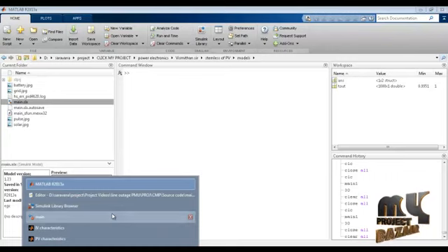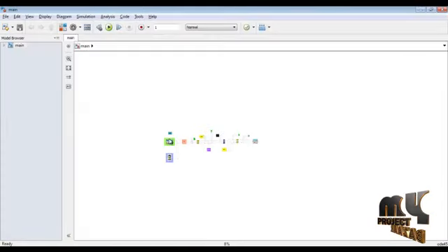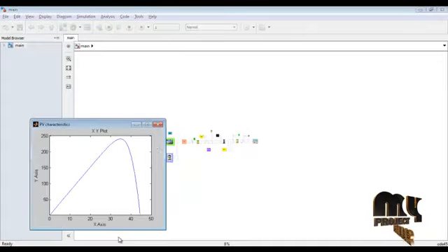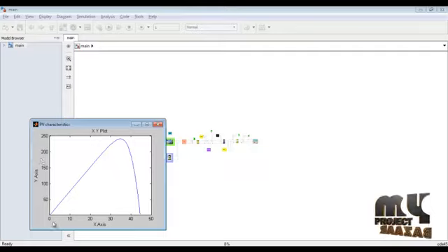This is the general architecture modeling. The general architecture consists of the solar panel, battery, and voltage source converter, and the different models are gathered as per the circuit diagram of the paper, with the ripple filter, load, and grid, all implemented accordingly. Next we see the results. This is the PV characteristics for the solar panel. The x-axis is voltage and the y-axis is power. It reaches nearly 232 or 240, the maximum power we can attain from the solar panel.